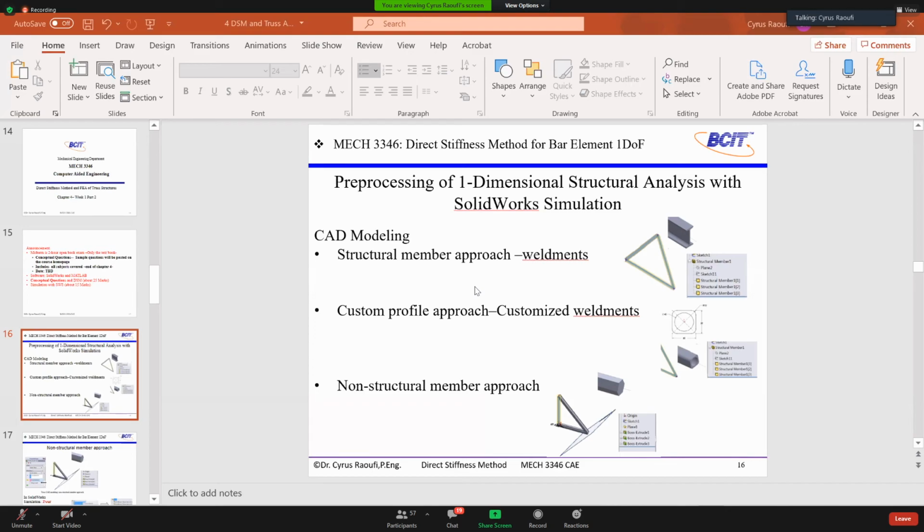When we're talking about beam or truss, we have to be careful about the definition of beam and truss. We are going to look at what we learned in our strength of materials course, and also statics. If you remember, the definition of a beam is clear. We can treat any member as a beam as long as it has a long or slender shape compared to the largest diameter in the cross section. And that was the ratio.